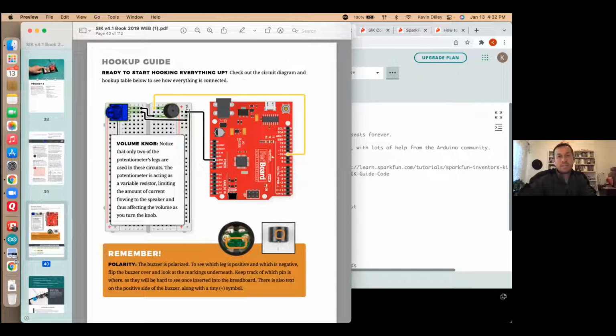You can see here on the wiring diagram kind of what it looks like. For these, it also is polarized. So it means that electricity has to go through it in one direction to be able to get it to work. The way that you can tell which side is plus or minus, if you look on the bottom of it, and it shows it here down below, it'll have a plus or a minus sign. The one I have is in kind of a copperish color.